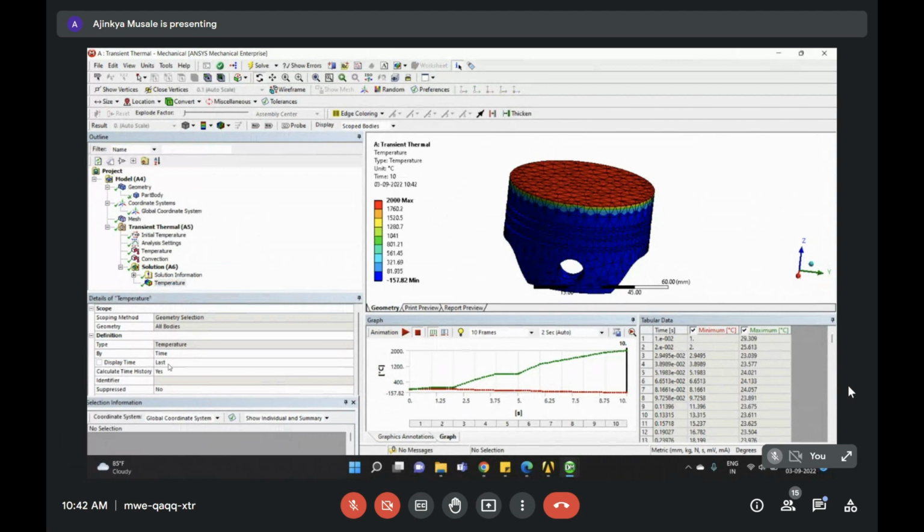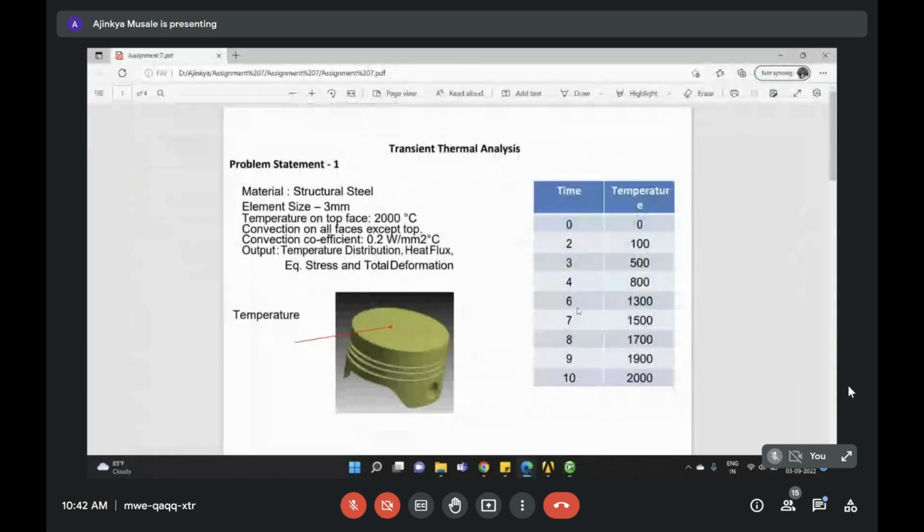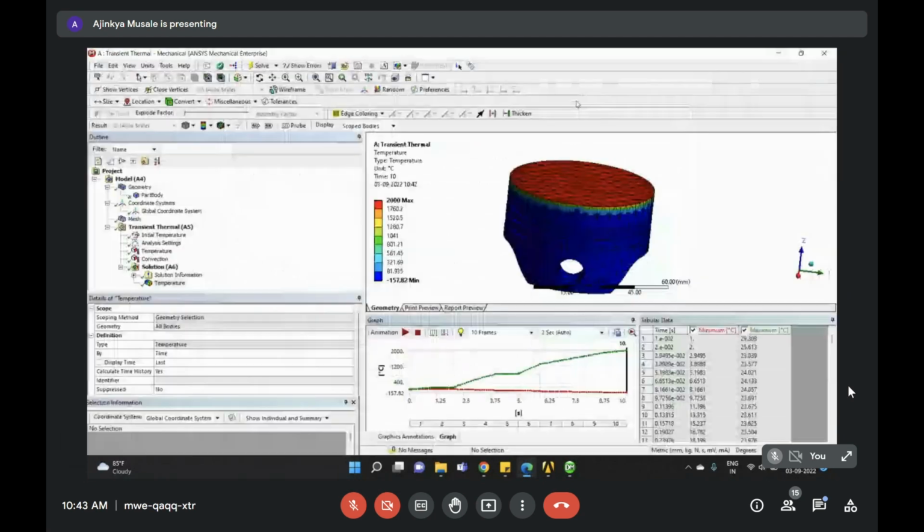The important thing I told you regarding transient calculations is that I can extract results wherever I want. So if I want my calculation at the end of this fifth load step, maybe somewhere here after 1300 degrees Celsius, I can do that.